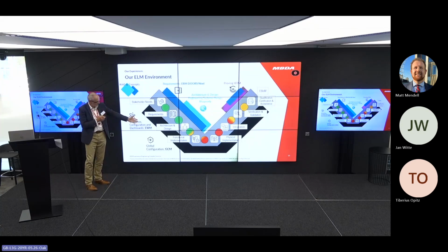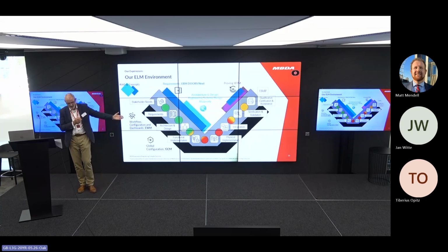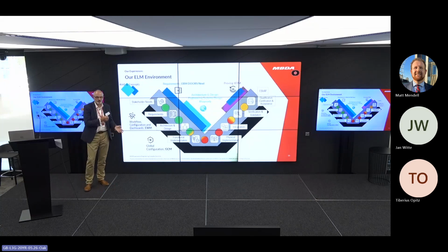I mentioned down the bottom left where it's sort of amber into red. I think the software aspects of that and the algorithms will get greener. We're still working the link between the Rhapsody and the MATLAB Simulink, such that your Rhapsody model could be a specification for your algorithms, for example. It's all traceable, and that's the important word, traceability. So from a requirement through some architecture and some design down to the algorithms and the software, it's in ELM, so it's traceable.